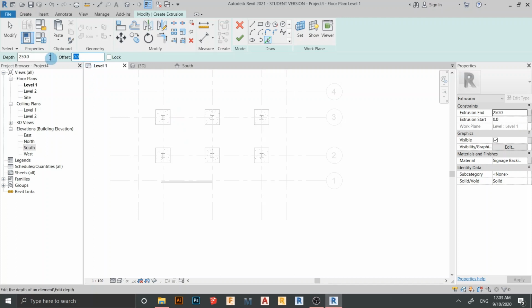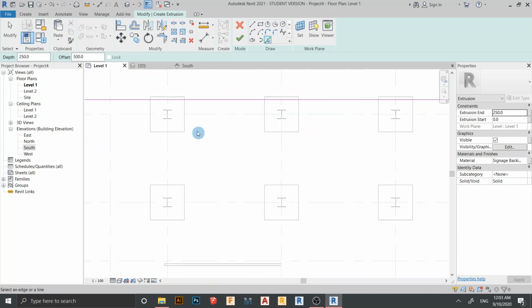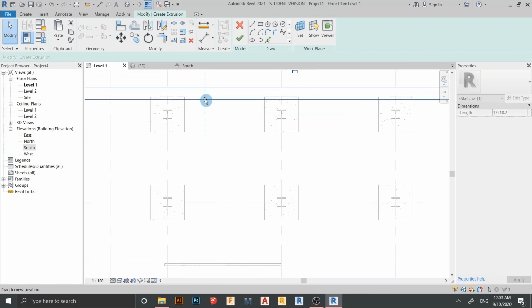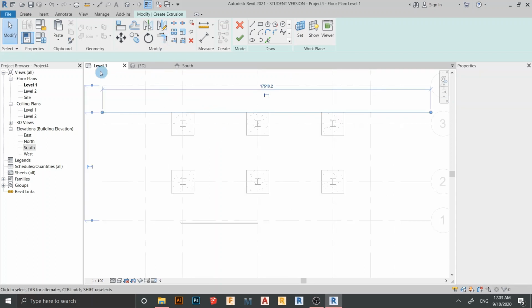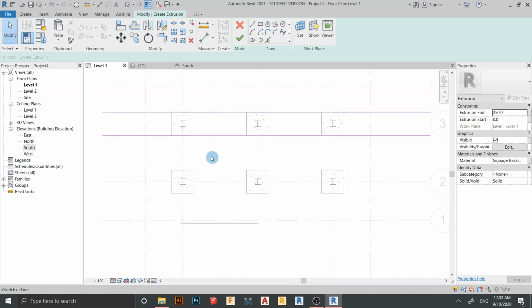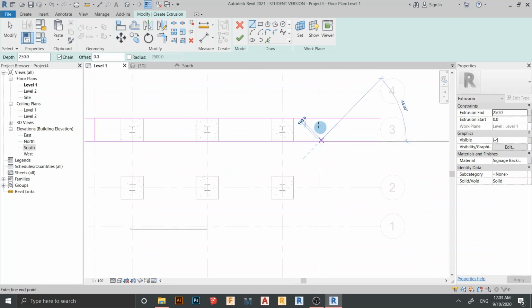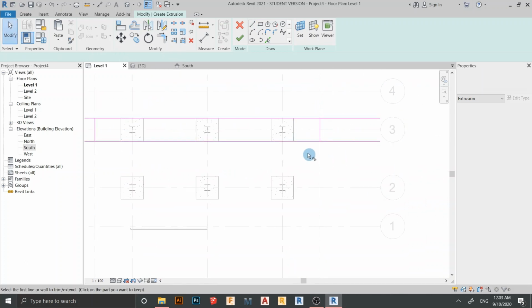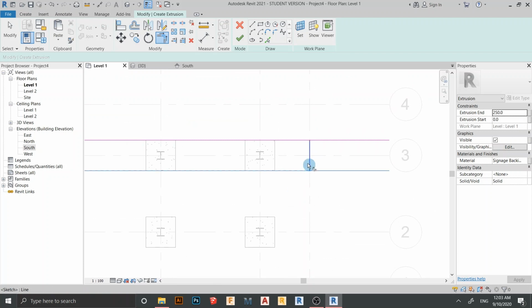Offset this one for, I think, something like 150mm. Too small. 1 meter. Too big already. 100mm. This one also too small. Yeah, we just leave it, make it balanced. Select this one. Draw mirror. Select this. Start connecting from here until here, and here until here. TR on my keyboard for trim and extend.